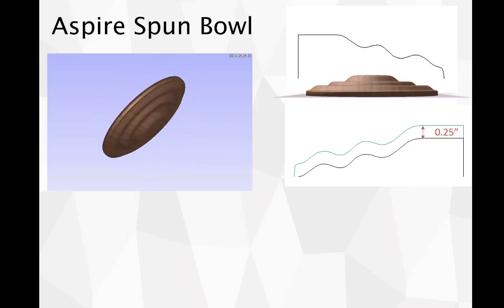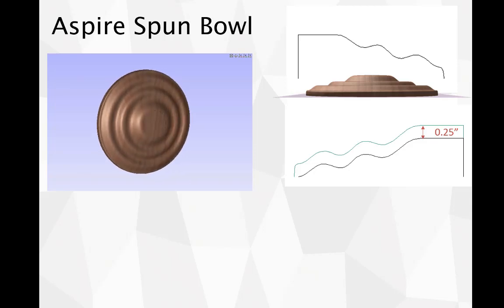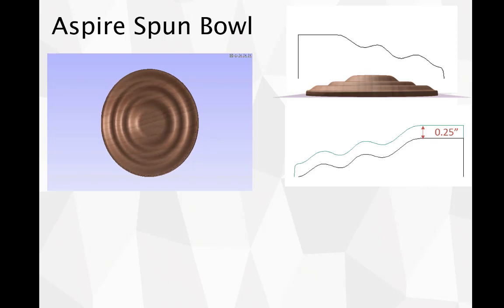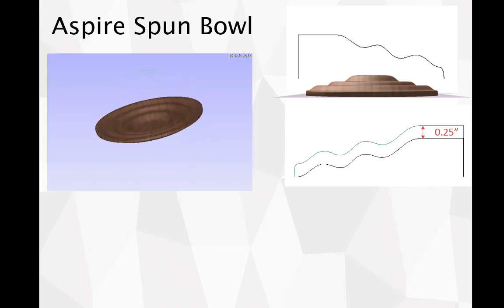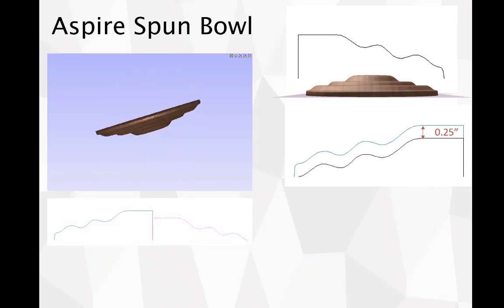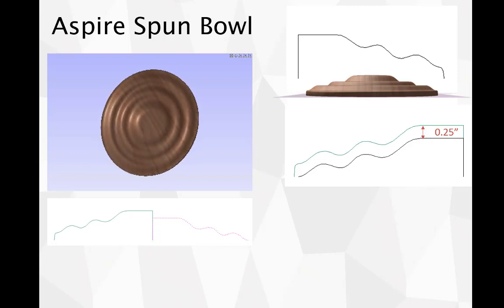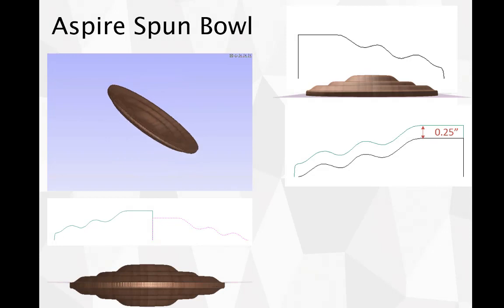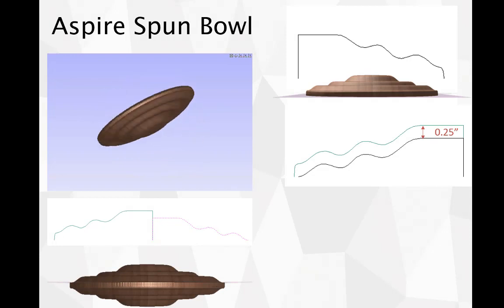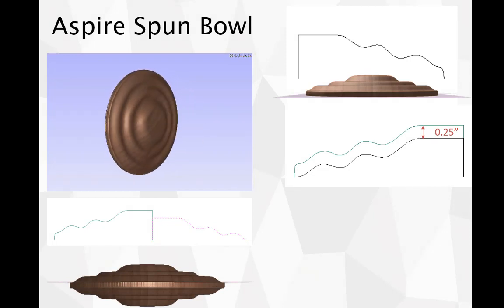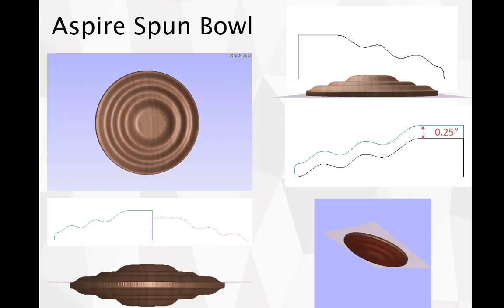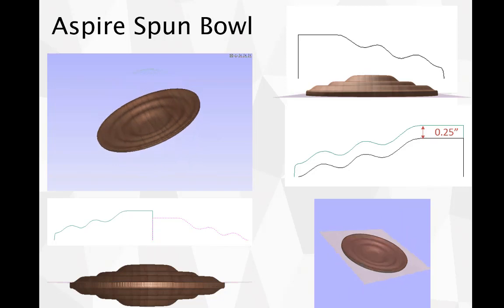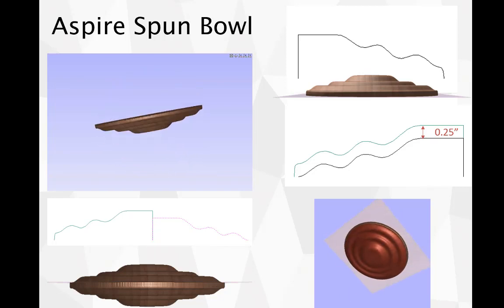And then using the Spin tool, we can only spin the part around the left side of your vector cross section. So we need to ensure that we position it so that the left side is at the center of my job that matches the original vector on the other side. So then we'd spin that, and you'll see it will create a positive shape that would look like this, and then all we'd need to do is just alter the combine mode so that it's subtracting, and there we have our bowl. So let's show you how to do this in the software.